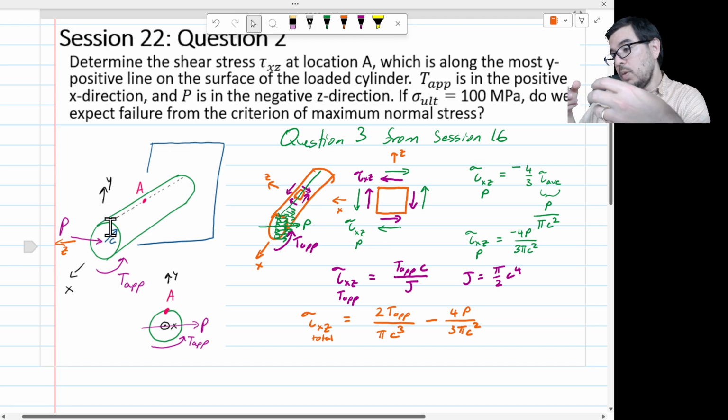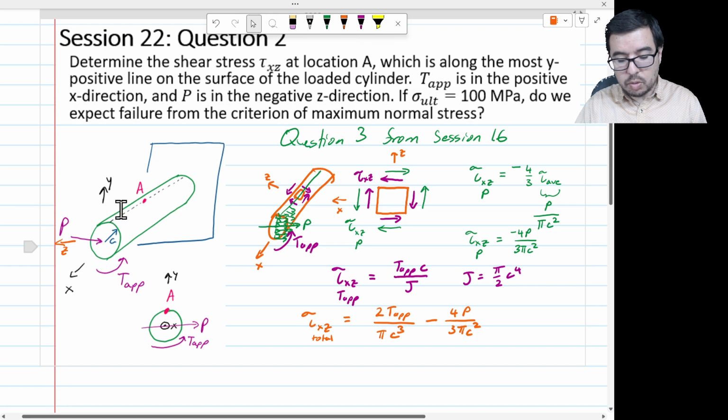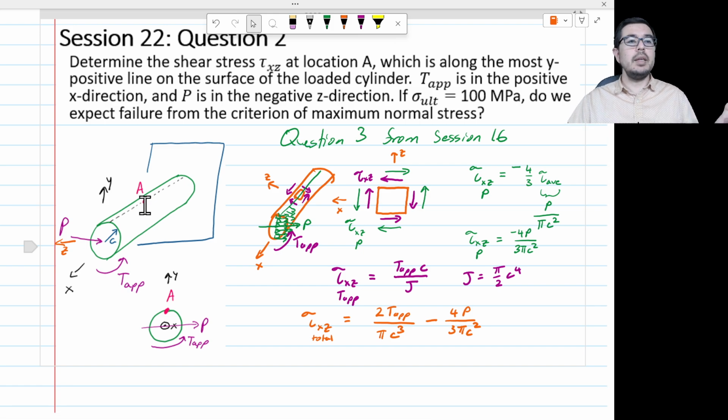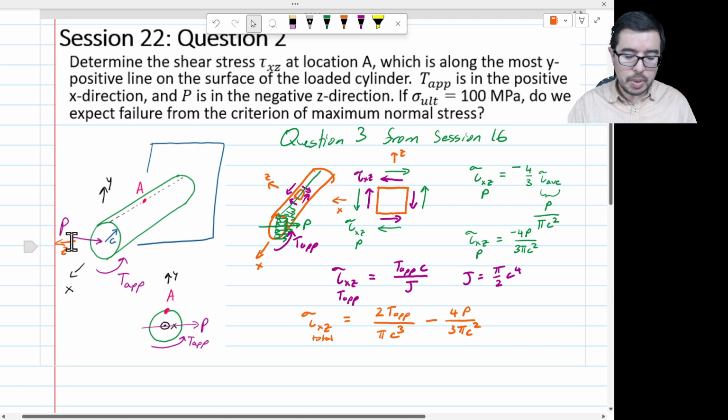Yes, I'm on the neutral axis here, or the longitudinal axis, this dashed line. If I come across, that's the neutral axis. So if y equals 0, where you're at a location on the neutral axis, then the bending stress is going to be 0. So there's no bending stress due to P. And we've got the transverse shear stress due to P. So that's it from P.